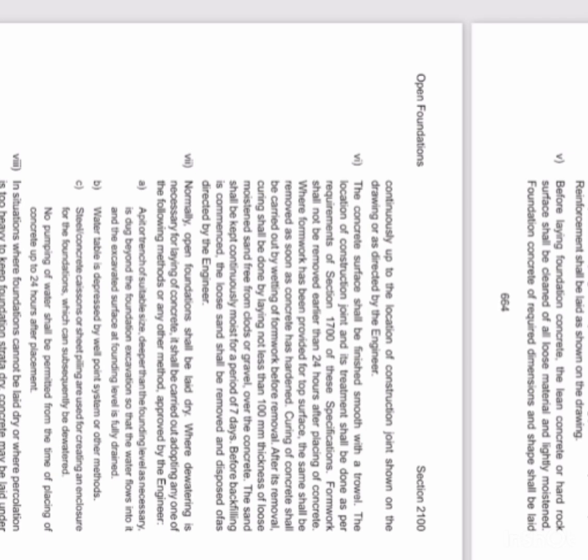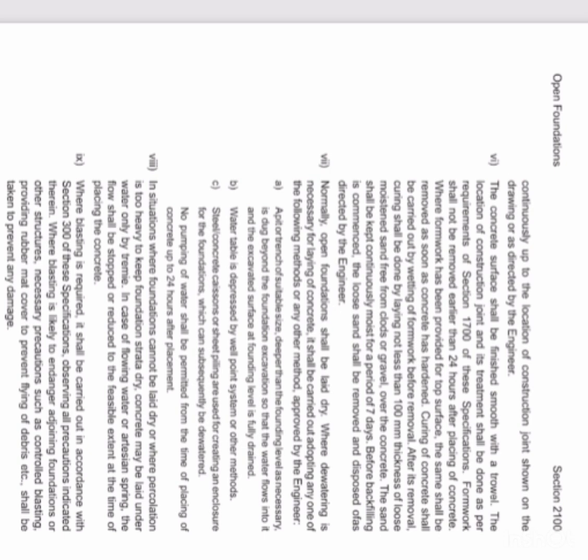Where dewatering is necessary for laying of concrete, it shall be carried out adopting any of the following methods or any other method approved by the engineer. A pit or trench of suitable size deeper than the founding level as necessary is dug beyond the foundation excavation so that the water flows into it and the excavated surface at founding level is fully drained.